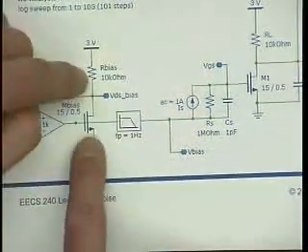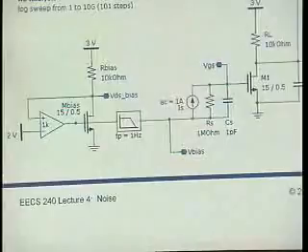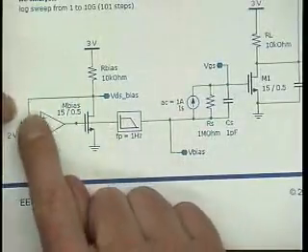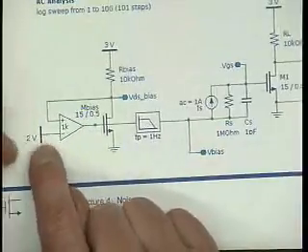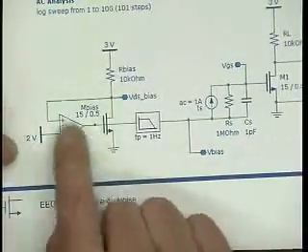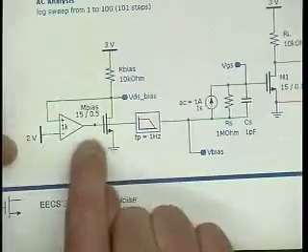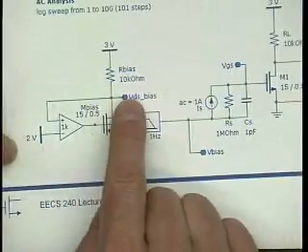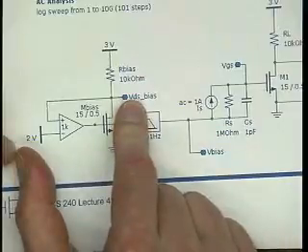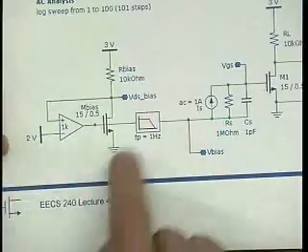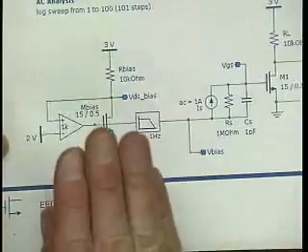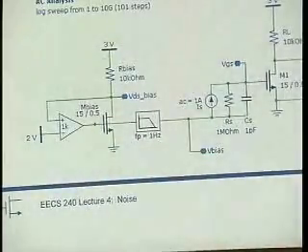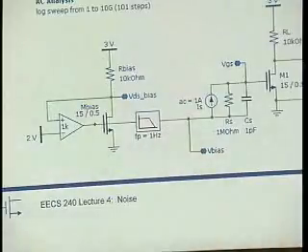This circuit is exactly the same, but I have set it into unity gain feedback, such that this feedback circuit computes the voltage required on the gate so that the output voltage is equal to 2 volts. Of course, in SPICE, it's trivial to do this. This is purely for biasing. We're not going to build this. It's just so that I can run my simulations efficiently without worrying about what voltage I need to put there.